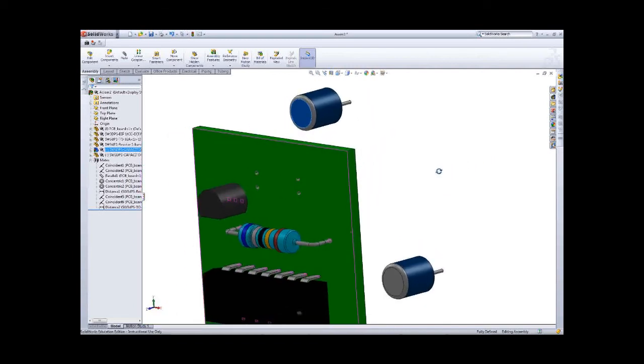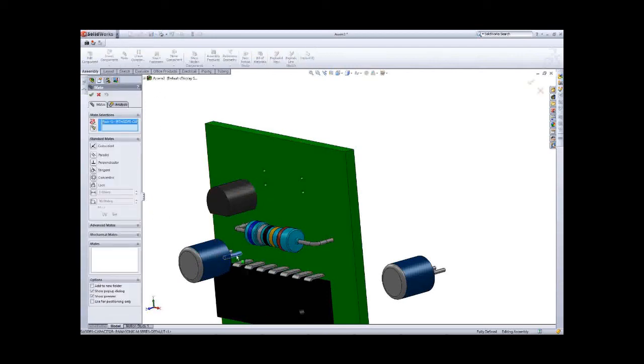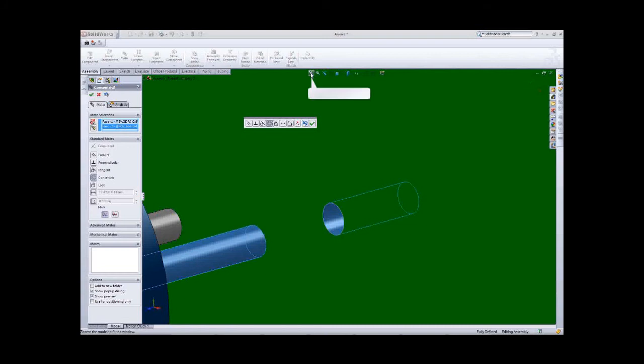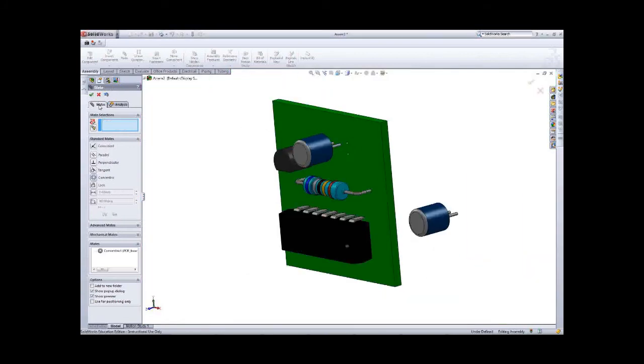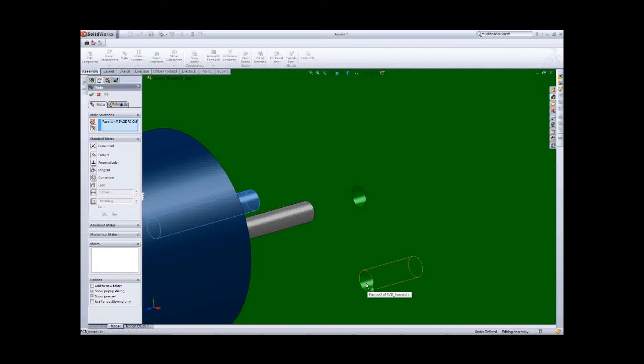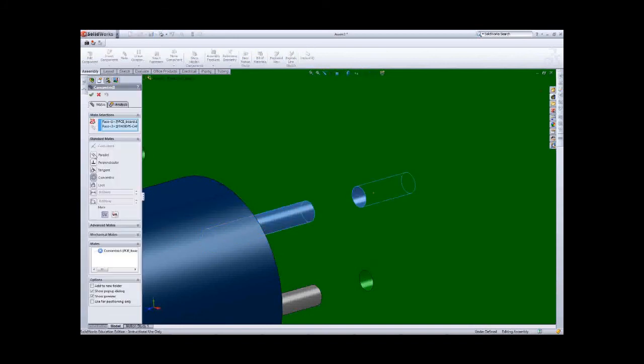One is face to face and then face to face again to fix it, because we have got the cylinder here. That one, we use the mate and then face to that face. And the other one is that face mated with that one. You can see coincidence again, concentric again. If you use the coincidence, you can make the distance, because that one you can edit it. And then because you just got a few defaults here, maybe face to face you can use